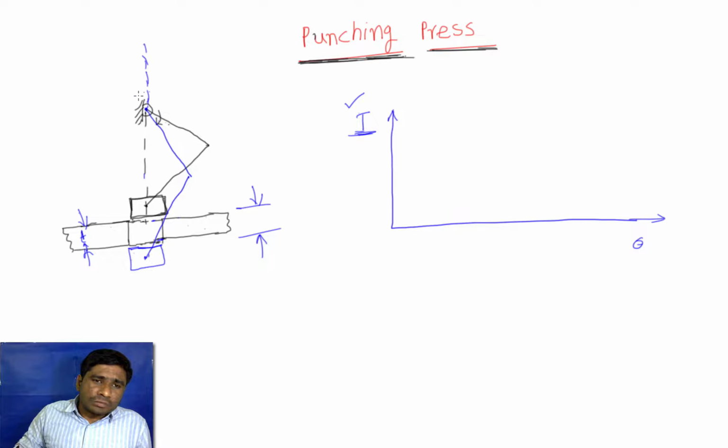It is not T produced or T given to the crankshaft. For example, let me call T given to the crankshaft is Tm, and if I consider this as a two-stroke engine, so in a two-stroke engine we have a cycle per 2 pi, or crank rotation per 2 pi.